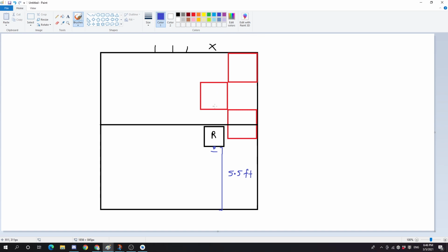Basically, what we want to do is say that if we're at the starting line, we know we shoot at some velocity. But what if instead of our robot being over here, it was somewhere over here? Would it still be able to shoot the same distance, right? There are two main components here. One is adjusting the way you shoot. Again, this is done by your shooting speeds, your flap, your angle adjuster, whatever. The second thing is also turning to your target.